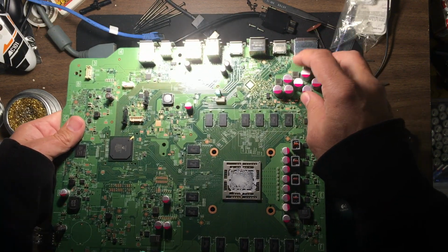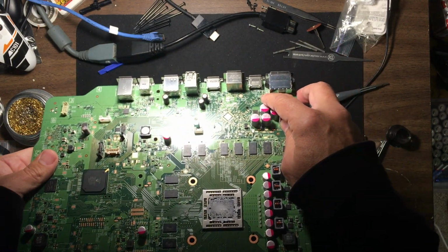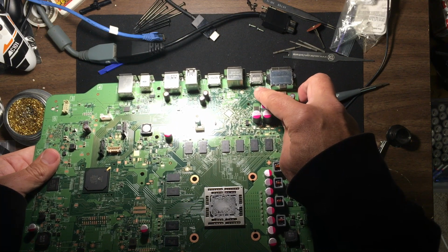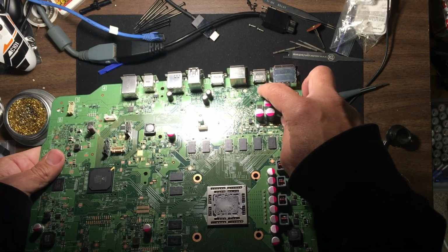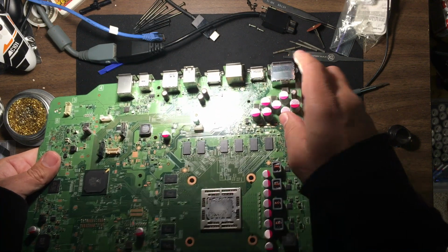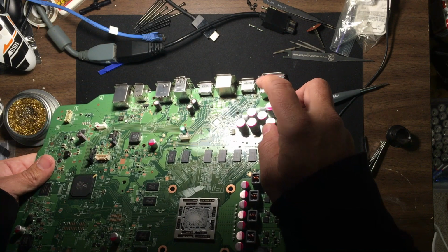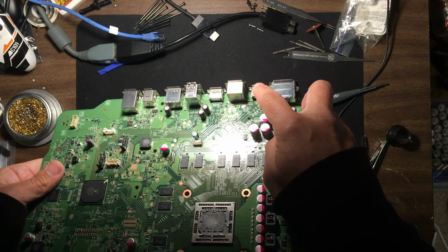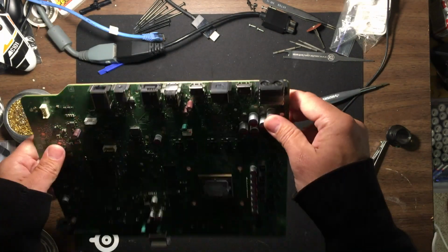With the low melt solder, we also have to be careful. You can see there's a couple chips in there. I don't know if you can make that out, but they're very close to those ports, and the low melt solder goes everywhere. So it would very easily remove these components as well. Looks like there's some tiny capacitors, and there's enough room, but you just have to be very careful doing this because you could make the situation worse very easily.